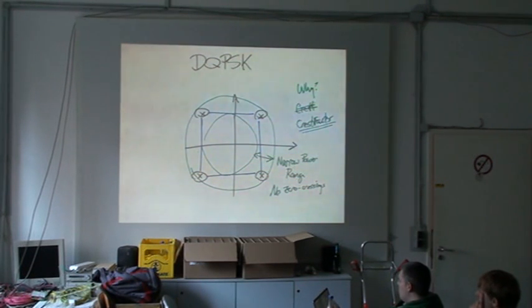This is why a crest factor larger than about 4 leads you to waste a tremendous amount of power. Your crest factor is basically the factor of power that you're going to waste in your power amp, in order to have enough headroom not to distort and clip when these high-powered peaks go through it.